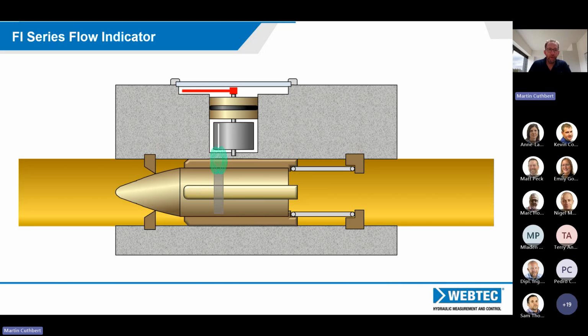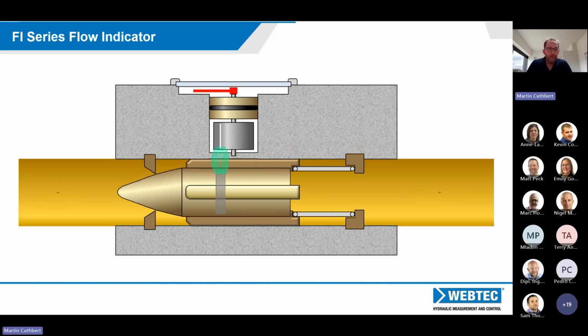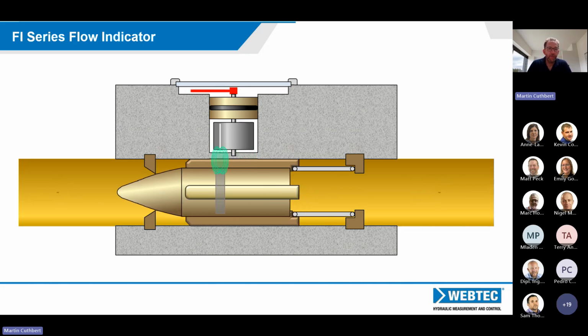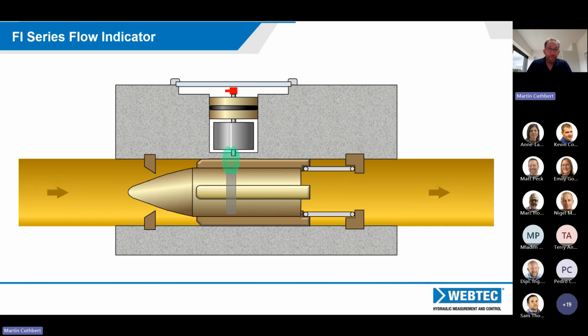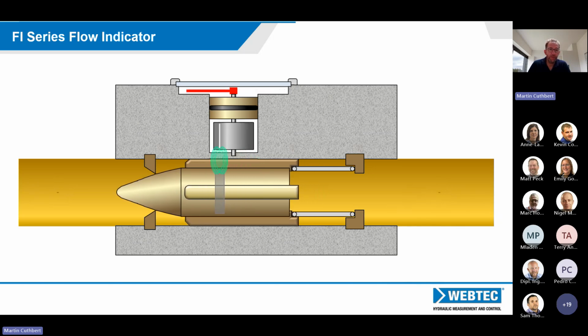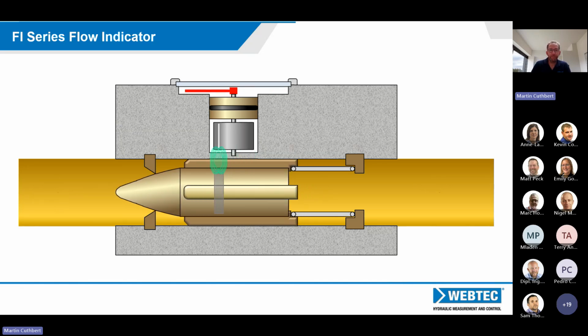As the flow accelerates, it will push the piston across to allow the flow through, and the linear magnet inside the bottom half is attached, rack and pinion style, to the rotary magnet you can see at the top there, which rotates the dial. Simple but very effective, very good at telling you what's going on in the circuit. With no batteries, it's simply using some of the energy from the oil, so there's a small pressure drop across it in order to move the piston against a spring.